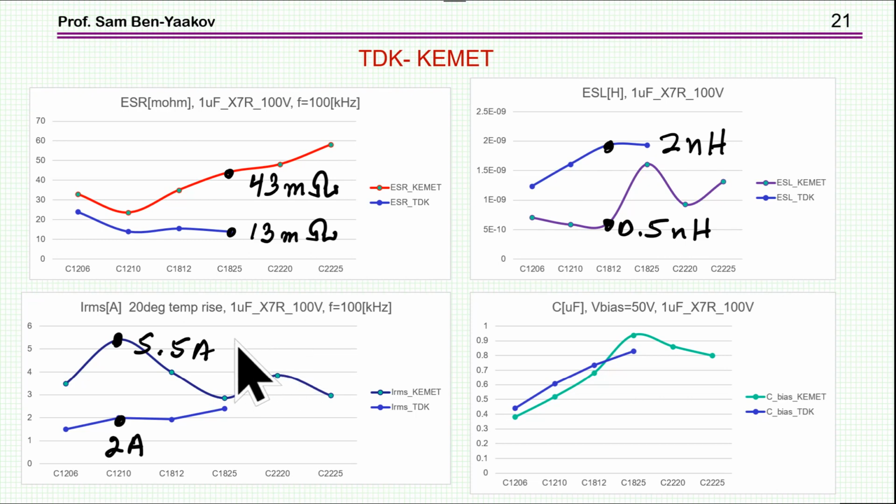So obviously, I would suspect the Kemet is measuring the capacitor while it is mounted on a PCB with a lot of copper area around it, and therefore they can pass that much current as compared to the TDK, which must have a much, much smaller copper area.